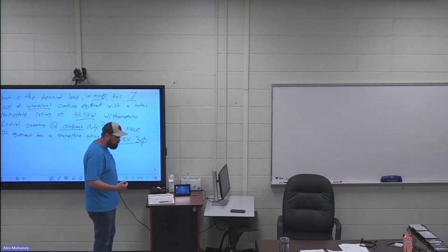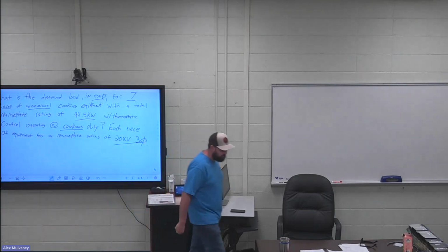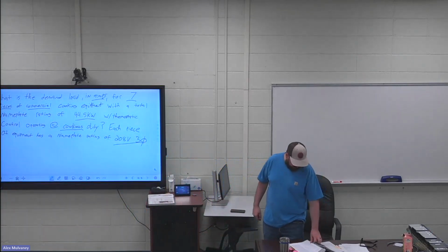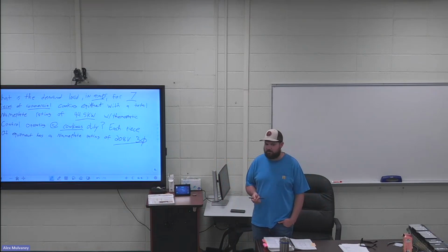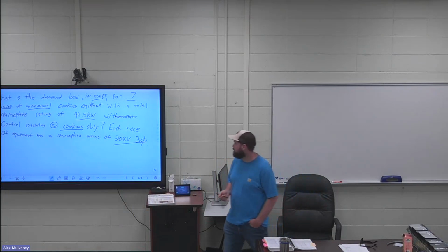So now I need to go look at that table, right? 220.56. What does that give? 65% demand factor. Can anybody explain to me what demand factor means? So we're multiplying this by 65%.